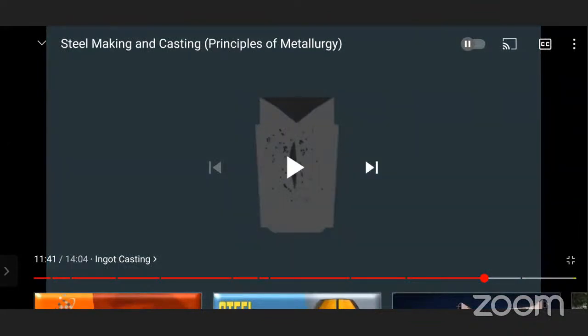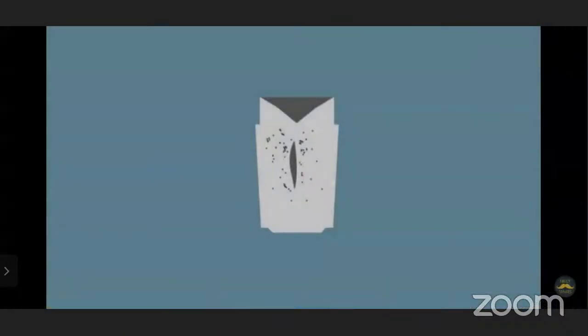So there will definitely be holes or voids or different gaps in between, due to shrinkage and gases liberated from the operation. A large feeding pipe defect is cut from the ingot, but most porosity in the ingot is acceptable since it will disappear through further processing in the rolling mills or forge.